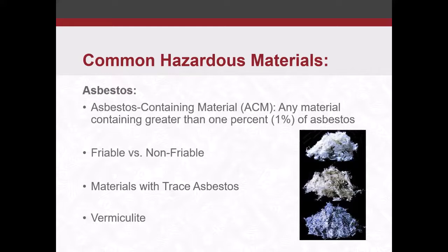You may have heard about the surfacing type materials, your spray applied fireproofing type materials. That doesn't really apply specifically to them. We do have analytical methods that you can use to see if that would be classified as asbestos containing material, which is important because, as you can imagine, in some high-rise buildings there is a lot of spray applied fireproofing. It's friable material. If you can do that additional analysis and prove that it's not asbestos containing material, that saves a lot on your abatement. It saves a lot on the cost for renovation and demolition work. So that's the difference there. There are some methods for surfacing materials, but there aren't any current methods for your loose fill vermiculite.